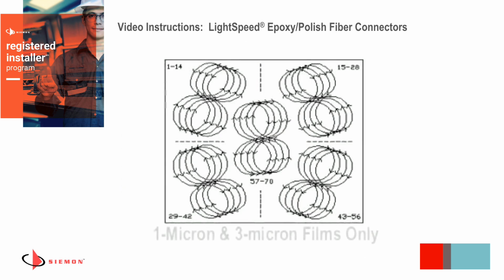To optimize optical performance of the connectors while maximizing polishing film life of the pink and purple films, use separate sections of the film per 14 connectors. Using 5 sections of the film as shown here assures a life of at least 70 connectors per film. Variables such as amount of adhesive on tip, size of figure 8, and polishing pressure can also affect film life.